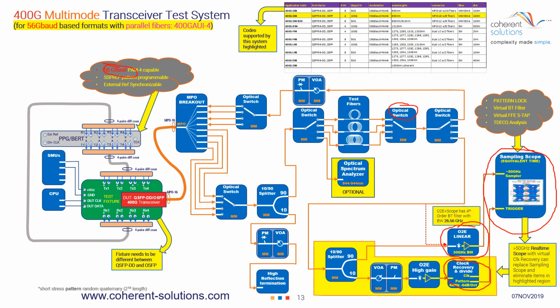The important thing to note here is that in the actual transceivers that are being used in 400 gig circuits, there are many feed-forward equalizers known as FFE 5-tap. What these do is recover the signals that would look really rather ugly if you did not add this equalizer after the fact.